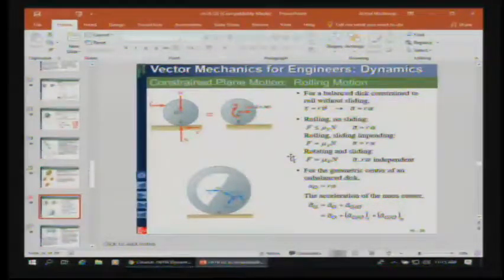Now this is kind of an important point, and Logan brought this up in the last class, but basically friction is only going to reach some sort of a maximum value. Even though it has the capacity to be stronger, it's never going to push you backward. It's never going to reverse the reaction, because it's always opposing motion. So what we're saying here is that if you have sliding impending, every bit of the frictional force available to you is going to be used. But when we go beyond that, we get to kinetic friction instead.